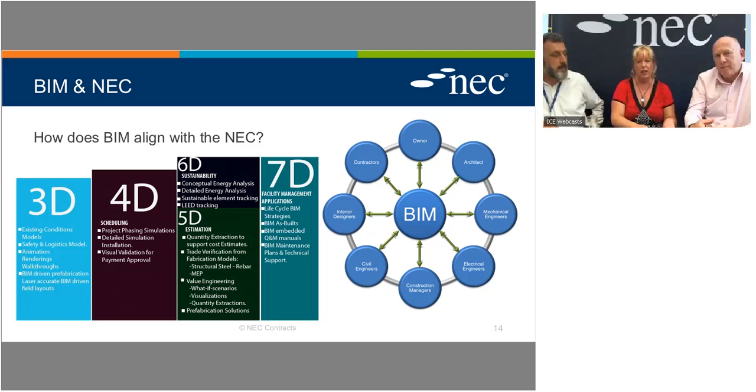Where I think BIM is particularly helpful, and can remove some of those remaining areas of confrontation within construction, is that you have a very visible output that can help the client side make their assessments. For example, if we're using 3D, 4D and 5D scheduling, as a project manager you can literally see what the state of the build should be at any one time. You can go and look out the window to see whether that aligns with the BIM model. You can tell from the price of work done to date, or a cost verification certificate coming through, whether it aligns with what the 5D schedules show the cost should be at any one point. So it's a very strong underpinning tool for helping the client side.